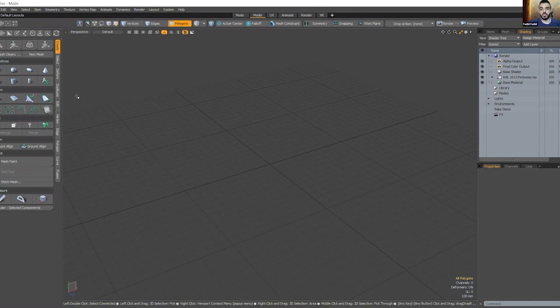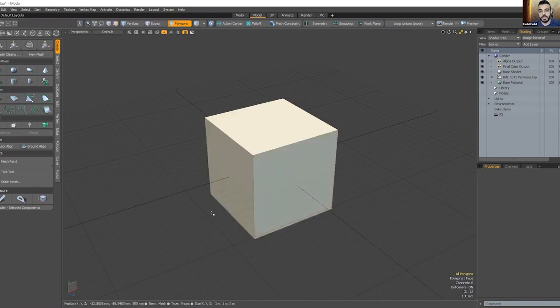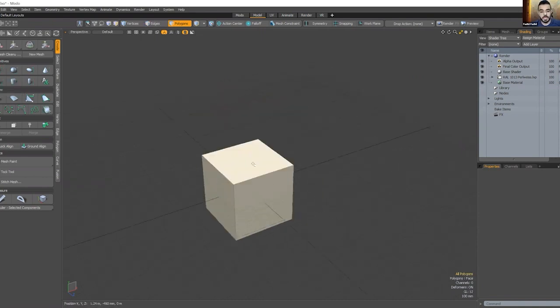So what I would like to do is go ahead and start with a primitive geometry. And the goal for this workshop is to create a wall panel that's ready to be prefabricated or fabricated right away, and has different interactive elements within it and integrated ecological system pockets. So I'm going to go ahead and start with a box. The way you start on the box is you can press Control and click on the box, and it lands immediately at the center of it.